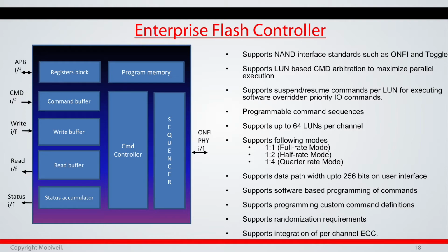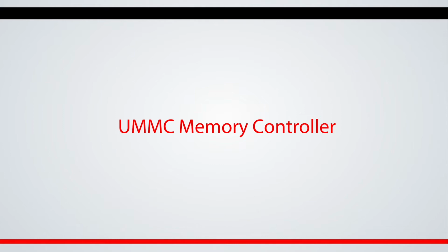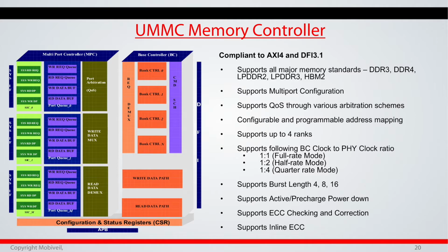And the controller itself should allow those commands to be executed in silicon. So we have this sequencer and the program memory where the customer can define newer flash commands in silicon and execute them. This is also very important. You can't have a flash controller today which you can assume will work, say, 2 years from now, because there are going to be new commands added. And of course, the flash vendor is going to have their own secret commands, which they will only tell a user. So this controller allows that flexibility where newer commands can be added. You can play with even the timing, and you can have ONFI as well as toggle. Both are supported.